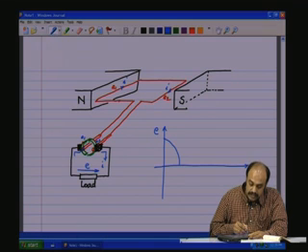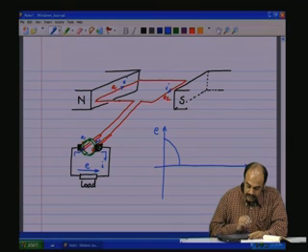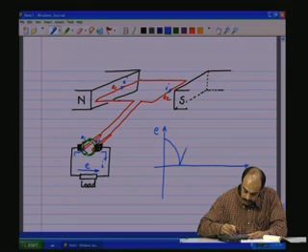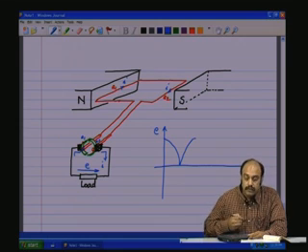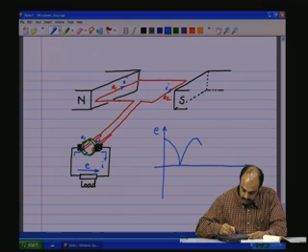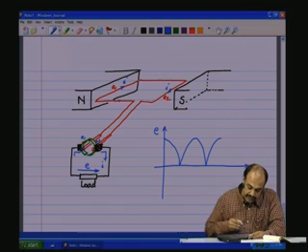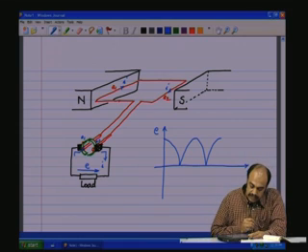The ring which was positive is now making contact with the other brush, and therefore there is a reversal in the contacts with the brush, which is again going to make the current through the load in the same direction, and this is going to go like that, and so on in this fashion. So there is a rectification which has come about due to the way in which this ring has been made.